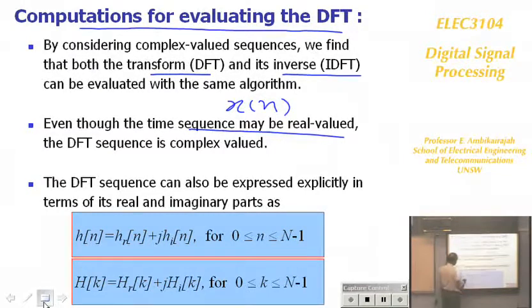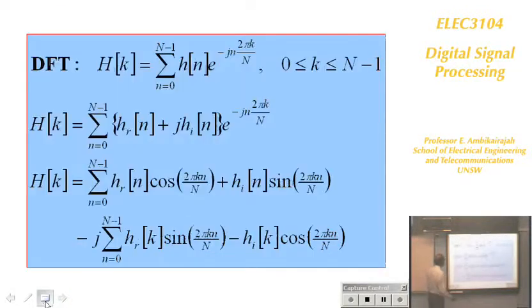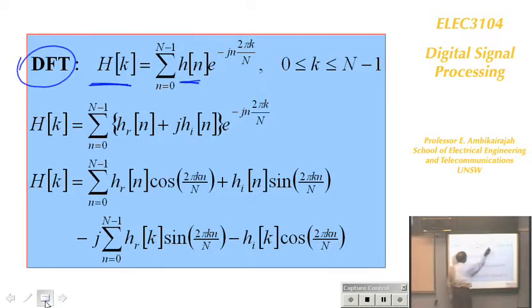So we could assume our signal is real as well as complex. When we do the Fourier transform, you get a real part and an imaginary part. That's how you get the magnitude response from that. So if you start with the DFT, H[k] is what we are trying to find, h[n] is your signal, and you write the equation. You now expand it; h[n] is real and complex. So I make it just complicated for you for a moment.